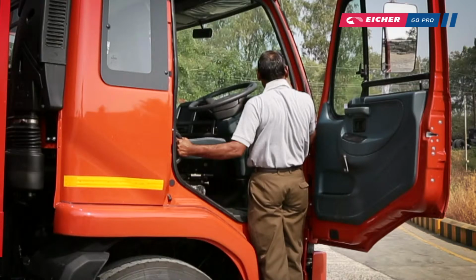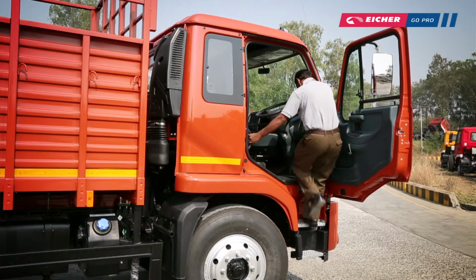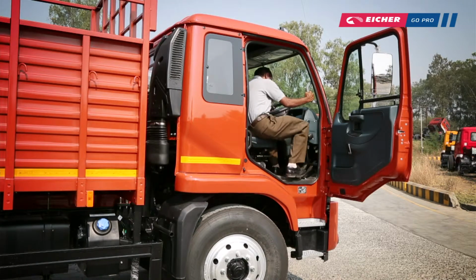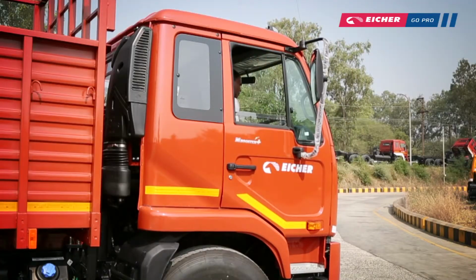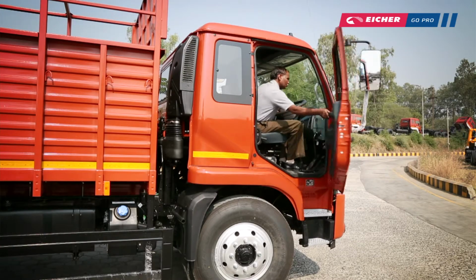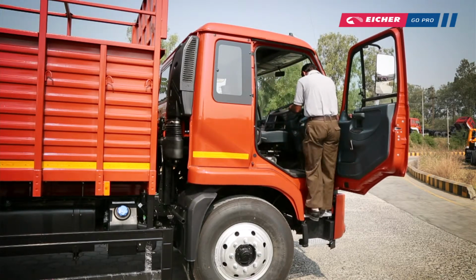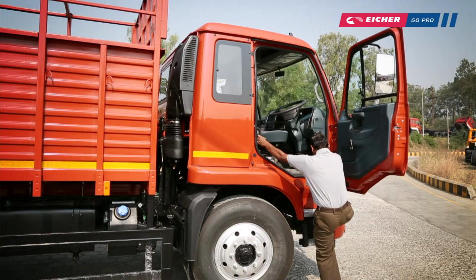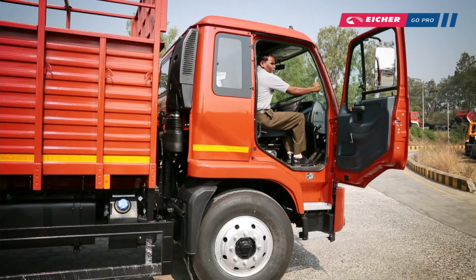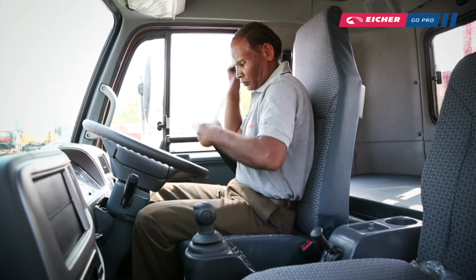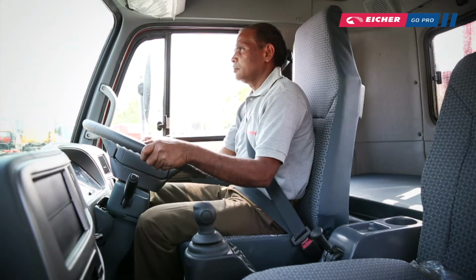If you grasp the lower handle with your right hand, then move your right hand to the upper handle. Step into the cabin floor, position yourself in the driver's seat and release your right hand from the front upper handle. To get out of the driver's seat, use the reverse process of getting in. This is called the three-point contact method. It means that at any time, two hands and one leg, or one hand and two legs, should always be in contact with the vehicle. It's important for drivers to wear their seat belt to comply with the law and to ensure safety.